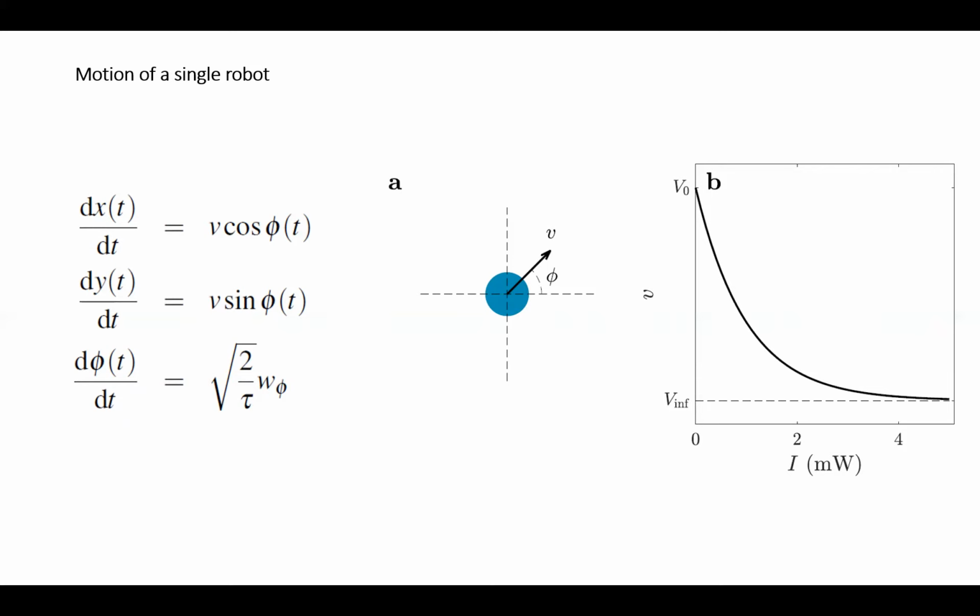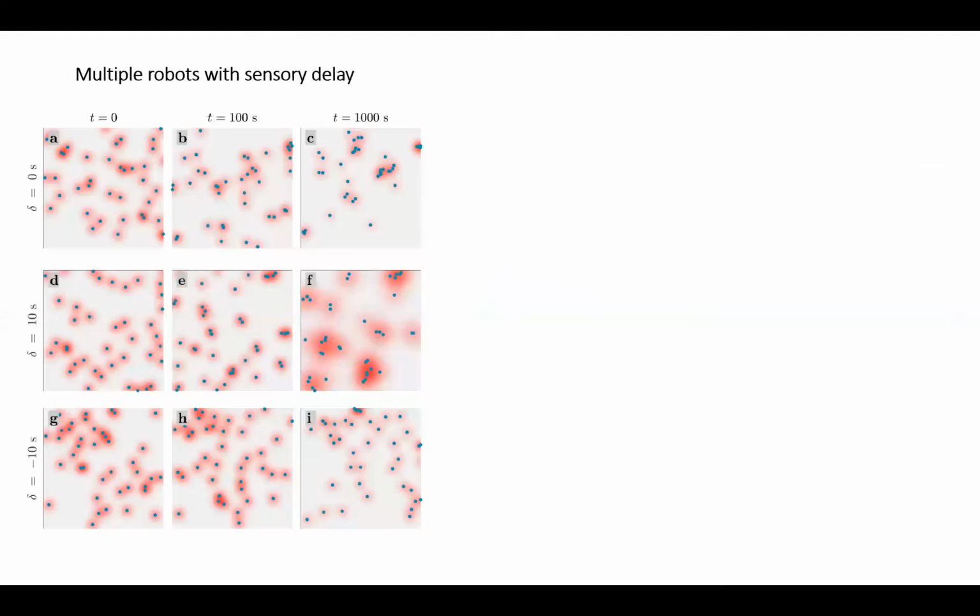You have multiple robots, and you have to create a map of light intensity. Whenever you measure it with a single robot, you need to subtract the signal that is generated by the robot itself. You first calculate the overall signal in the entire grid, the map created by every robot, and then whenever you measure one of them, you subtract the signal generated at the center by that robot. Is that clear? Instead of calculating for each robot separately, which is maybe what I'm doing in the example code, you can make it even more efficient like that. You calculate everything and then just subtract the one that is generated by each robot.